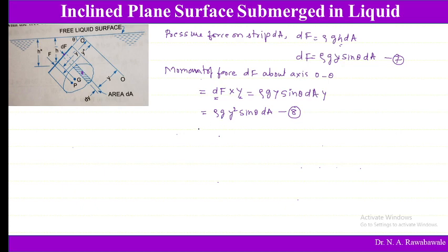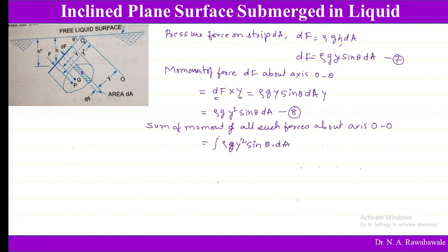So integrating the above equation, or sum of moments of all such forces about axis OO or reference line OO, we can integrate the above equation 8, that is rho g y square sine theta dA.